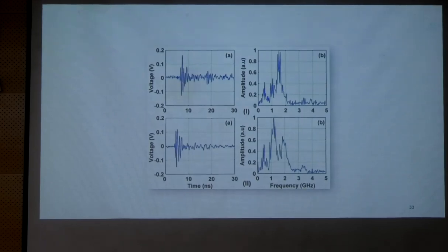With respect to severity, higher frequency bands also appear. At the inception level you may have frequencies up to about 1.8 GHz. At higher voltage levels the frequency shifts higher, to around 2.2 GHz. In that way we can use this for diagnosis.